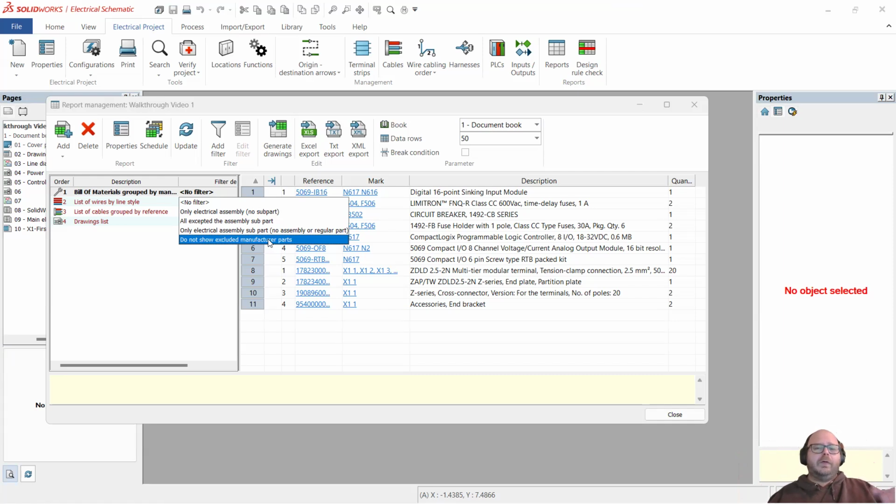The way that SolidWorks Electrical handles layouts is every time I bring in the back plane or the cabinet, it brings it in as each symbol. Like I need a front view of the cabinet, I need a side view of the cabinet. Well, guess what? That adds two cabinets. That is not good. So that hidden manufacturer part, I will create, say, cabinet XYZ, and I call it phantom, but hidden, right? Cabinet XYZ hidden. So I can use the hidden version for like the side view or a top view and not get three cabinets on my BOM.